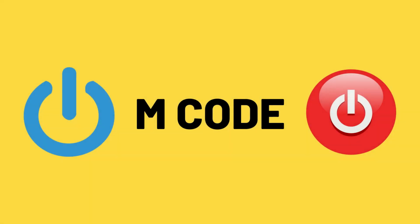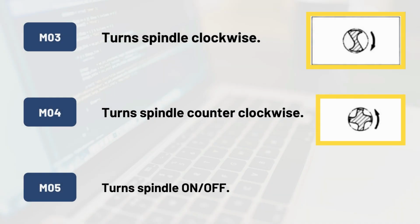Now, M or miscellaneous codes are used for either turning on or off different functions which control certain machine tool operations. M codes are not grouped in categories, although several codes may control the same type of operations, such as M03, M04, and M05, which control the machine tool spindle.